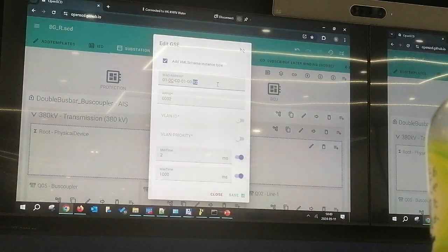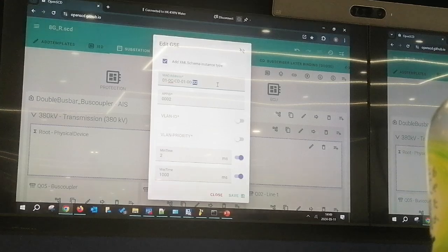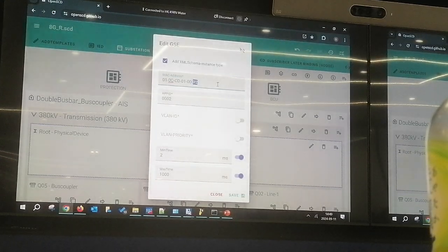Why should the trip be hanging around in the substation? We make a path for our trip. Trip only goes to where it needs to go, not everywhere else. We need to filter. The multicast MAC address is a mechanism that goes more or less everywhere, but we don't want that. Then we want our cable only connected to the correct place. Did I answer the question?